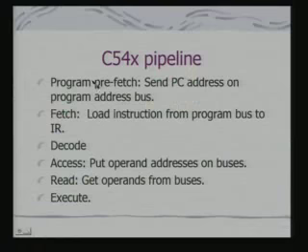It is a pipeline processor because obviously any of today's modern DSPs, just like your general purpose microcontrollers which are targeted for embedded systems, here also I shall have pipelining because pipelining increases the instruction throughput. In fact, it has what we call a program prefetch, which sends the PC address on the program address bus.